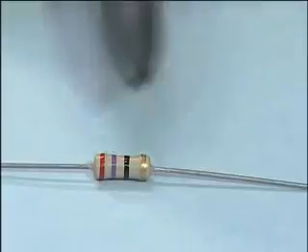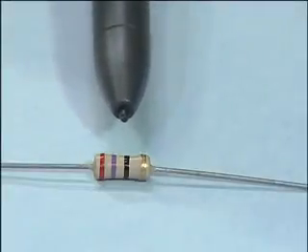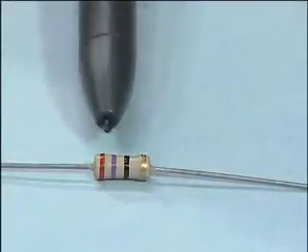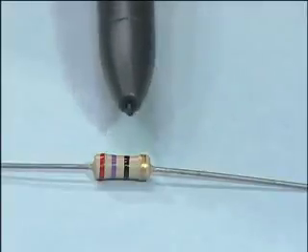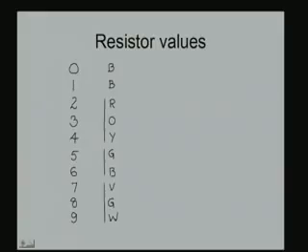This is a carbon compound resistor, a half watt resistor. You see that there are some bands on the resistor, some red band, violet, black and so forth. The resistor value is recognized by the color bands that are drawn on the resistor.